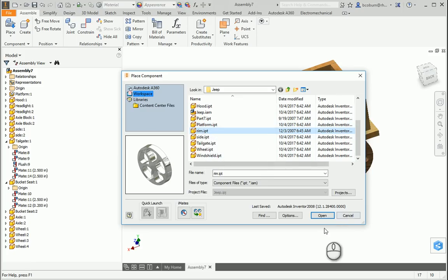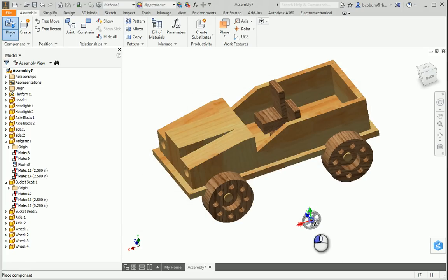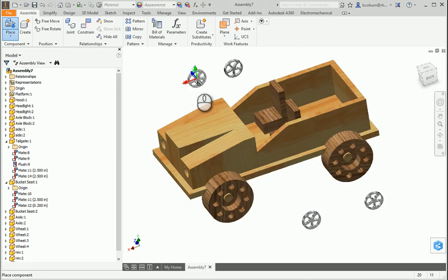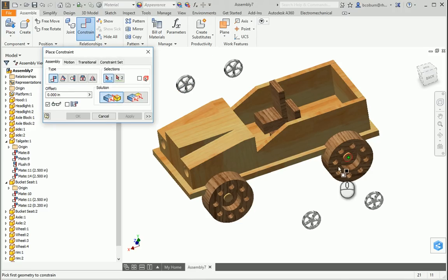And I'm going to open 4 of those, as I put them on the other side, just because I know that's where I'm going to go. Hit C for constrain. And it's key when I hit that insert that I go ahead and hit where I want to place it. See how I put the rims on there real nice and neat for me? In Inventor, it'll allow me to put them right on top of that. And now I have some rims in there.